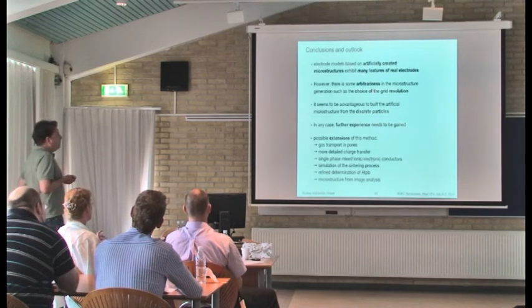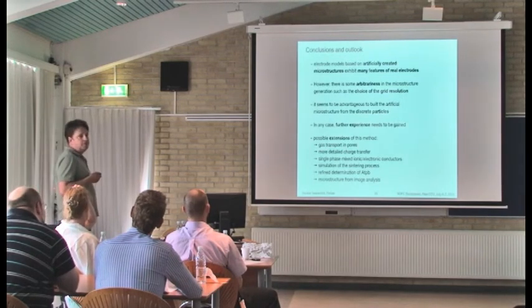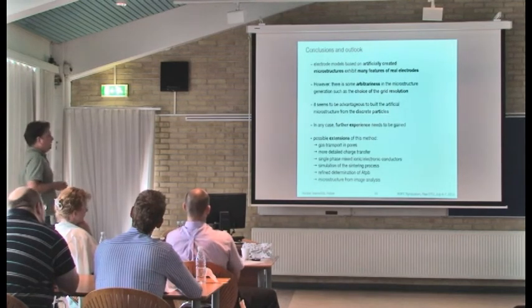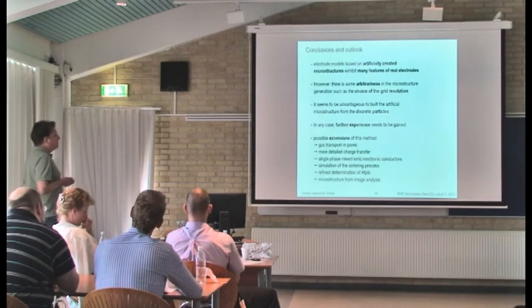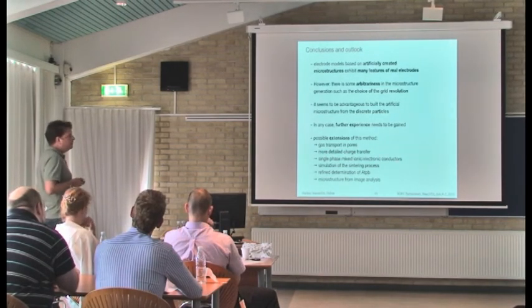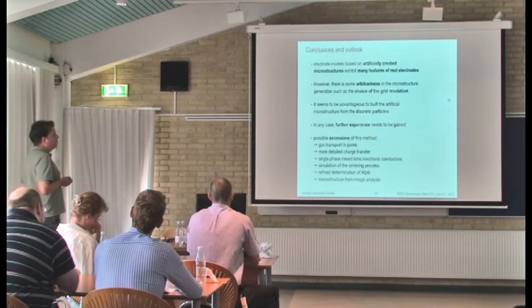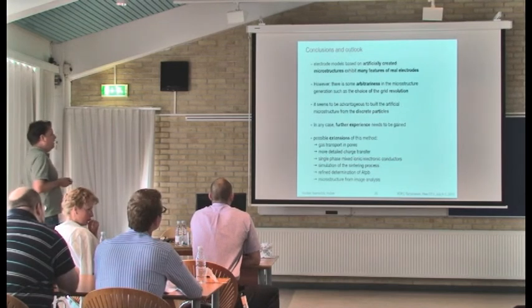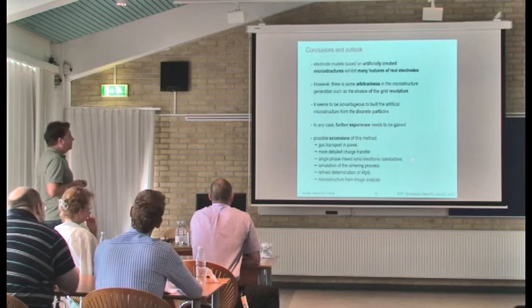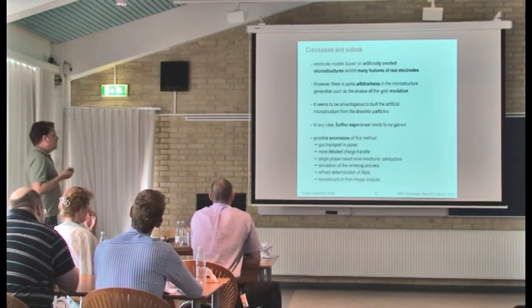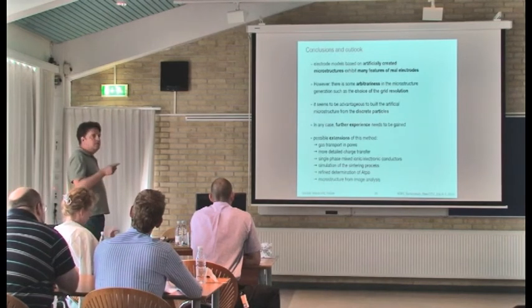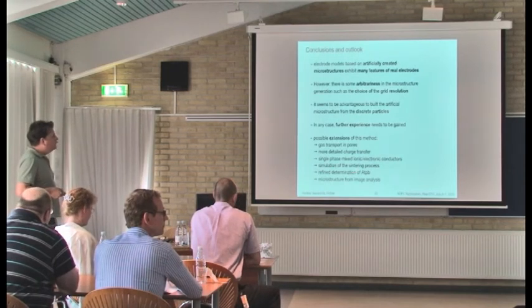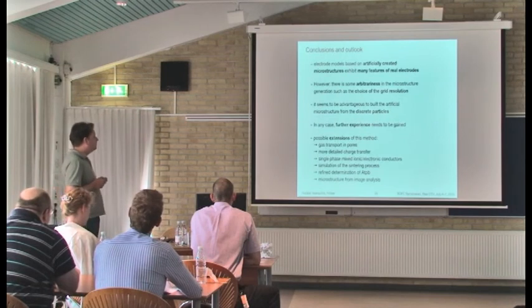So, what are possible extensions? You can now go ahead and, for example, simulate the gas transport within the pores instead of using the continuum model approach. This, of course, should be done, but it's clear that the model and the simulation times will largely increase. Also, for the charge transfer, you have different possibilities that should be exploited. We also want to go to single-phase mixed ionic electronic conductors to see what the results are there. And in order to generate the microstructure, it's also possible, and I think you made a reference to that, you can, for example, also simulate the sintering process. That's an interesting approach.